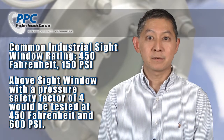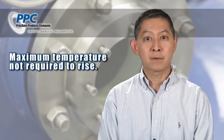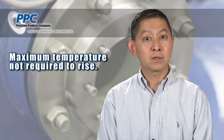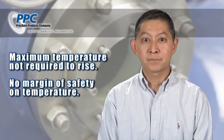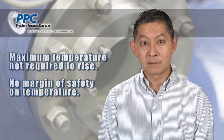The important issue here is that for this specification, the temperature is not required to rise above the unit's rating. In other words, there is absolutely no margin of safety on the temperature scale. Window materials turn to goo very quickly if you exceed their rated service temperatures. Think about that. There is absolutely no margin of safety on the temperature scale.